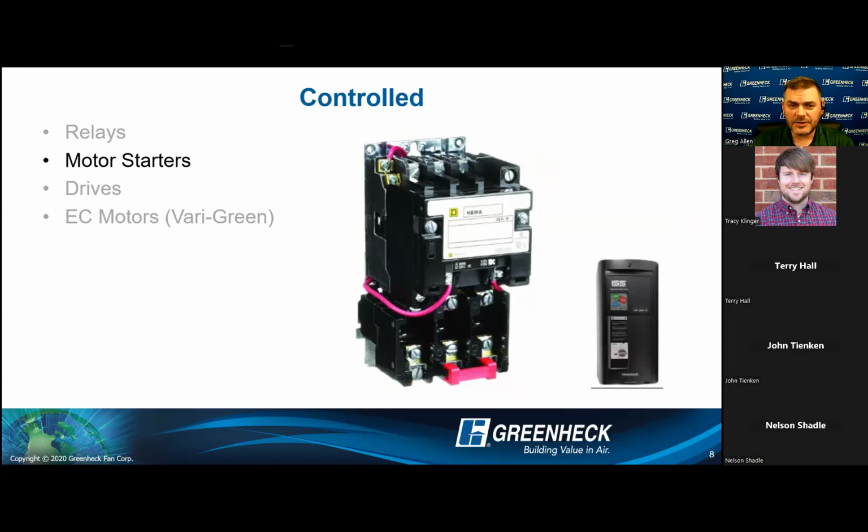If it's an AC induction motor, a motor starter is amazing. I have controllability. I can send it a voltage, or I can create a dry contact closure. If I have the right starter that can read those types of signals, it will activate its own contactor, which is kind of a big relay, and pass power to the motor. So now it's got motor control built into it, and I'm able to remotely take control of that.